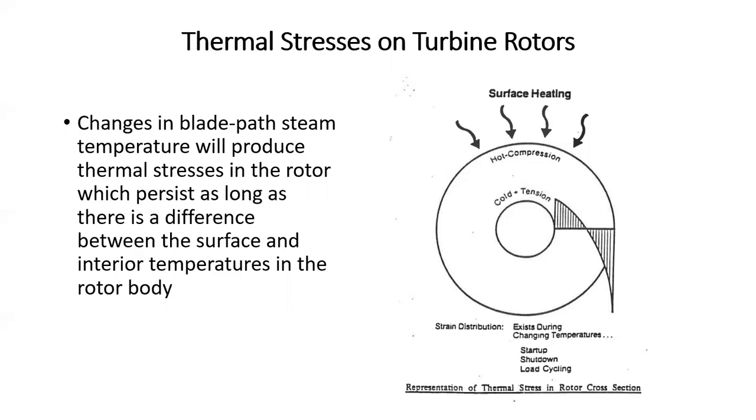And so you see that on the outer surface, we get a huge compressive stress, and then it declines as we go deeper into the body of the material, and then it switches from compression to tension and winds up with a fairly significant tensile stress at the inside of the bore. And so if there's a crack located there, then during this cold start where we're heating from the outside surface, that tensile stress is trying to pull that crack apart.